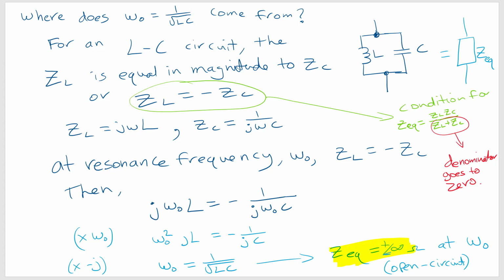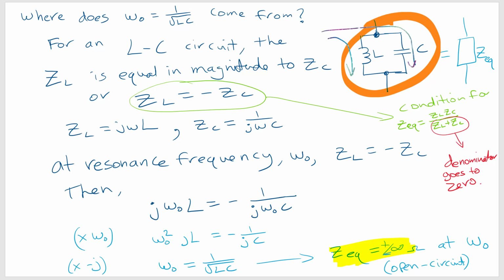And this circuit actually is a very, very important circuit. It's beyond the scope of the course to really discuss the applications, but essentially it's called a tank circuit. It's also an oscillator, and what it does is it acts as a band pass filter. So it passes frequencies at the resonant frequency. Lower frequencies get absorbed by the inductor, and high frequencies get absorbed by the capacitor, and intermediate frequencies pass through, the ones at the resonant frequency.